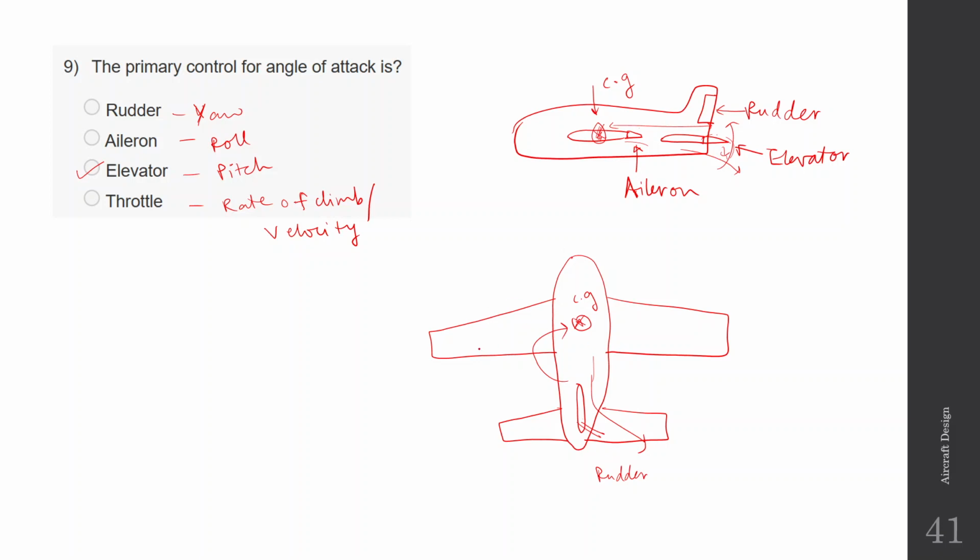And next we have the ailerons. So the ailerons are control surfaces which are placed on the main wing and a bit far away also. Again for similar reason, if we place the aileron very close to the CG, it will have lesser effects. So the ailerons are usually placed farther, on the wing towards the tips. And the ailerons are usually deflected in an opposite manner.